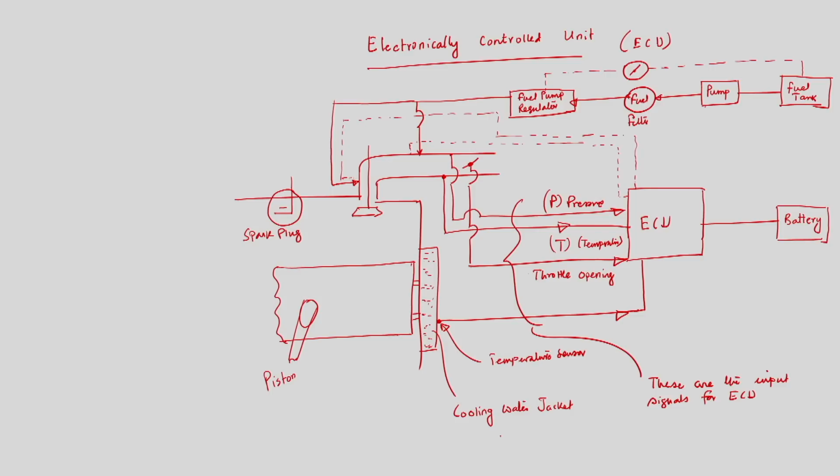The spark plug is very important. We have drawn the spark plug. This is the distributor. We have seen that we have a distributor rotor or distributor cam if it is a multi-cylinder engine, and the timing of the spark plug also will be connected with the ECU.